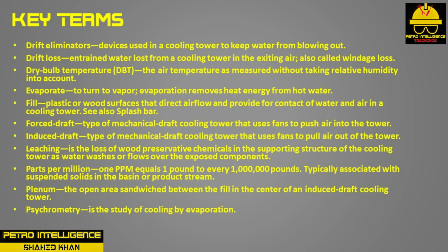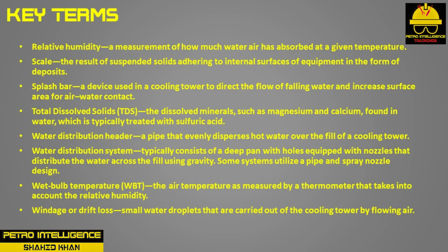Parts per million: 1 ppm equals 1 pound to every 1 million pounds, typically associated with suspended solids in the basin or product stream. Plenum is the open area sandwiched between the fill in the center of an induced draft cooling tower. Psychrometry is the study of cooling by evaporation. Relative humidity is a measurement of how much water air has absorbed at a given temperature.